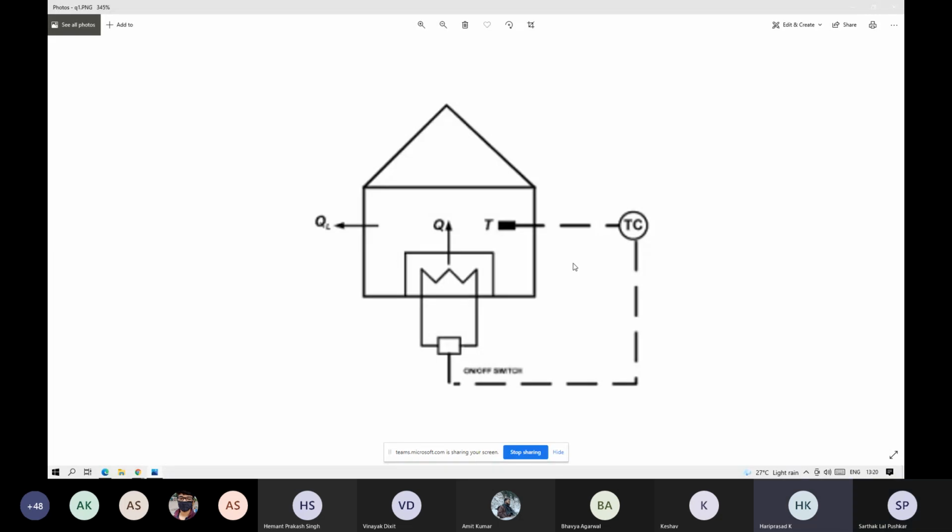So, Sarthak, I'll take that up. Consider any cooling system that you have in your home, for instance, an AC, except the inverter ACs. Most of the time, the operation of the unit would cut off when the temperature goes below your desired temperature, or it would start if it goes above the desired temperature. This is the same for any heating unit. I'm talking about AC, which is a cooling unit. Consider your water heater that is also installed in your home. It would work just like this.